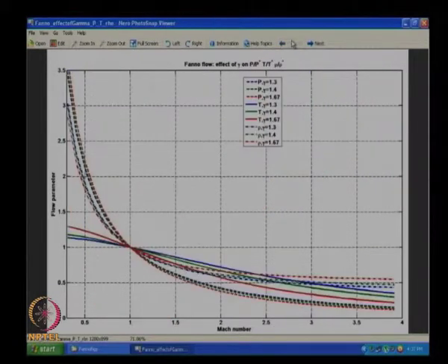Now, if you look at the remaining curves, pressure, temperature and density, I will first show this one. This is the temperature, the solid lines are the temperature, and you can see this is similar to what we will expect out of any compressible flow. With more compressibility, you are going to have temperature variation in one particular direction. This is for any adiabatic flow. We saw a similar thing even for isentropic conditions.